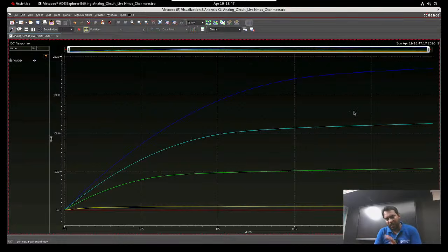Of course, you look at that graph a lot in circuit designing, ID versus VDS. It is showing a small slope because you are using a higher length. If you were using 45 nanometer, it would show a lot of channel length modulation effect, and lambda is high. So for reducing that and providing less slope, I am using a higher channel length for the 45 nanometer.